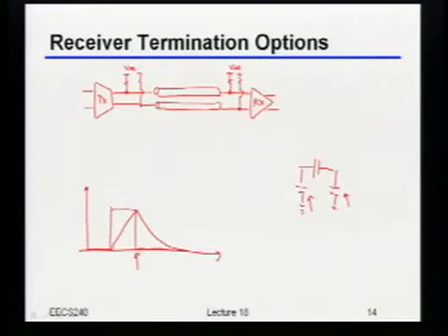So I'm going to meet the bit error rate spec? Yeah, and that should be basically the only higher level thing you have to meet, from my standpoint: the bit error rate spec. As long as you meet the bit error rate spec, I don't actually care how much gain you use, how much bandwidth you use, etc. We'll talk a little bit more about the trade-offs there probably right now, but from that standpoint, you just have to meet BER.